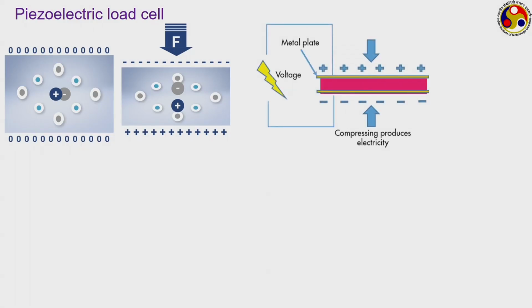if we connect them by an external circuit like this. That is, one side of the plate becomes positive, the other side of the plate has become negative, and now we are collecting them by an external circuit, and that gives some kind of voltage output or potential difference. And this potential difference, if we measure properly, can be found to be directly related to this force. I have mentioned there, I can clearly remember, that piezoelectricity is a very modern and important branch of measurement, and lots of research is going on in this particular line, and commercial devices are also available, simply because this is extremely advantageous from several contexts.